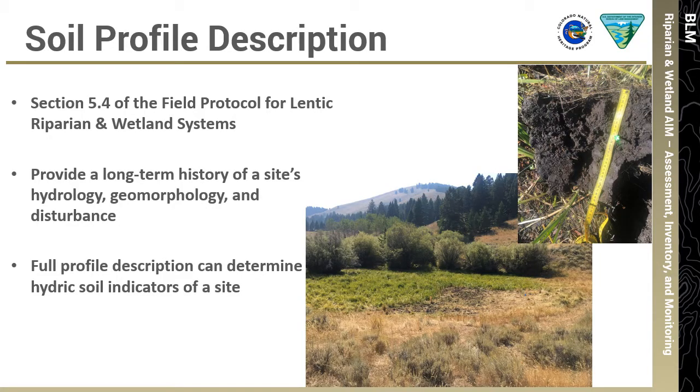Soil profiles are an important part of understanding the long-term history of a wetland site. Soils within wetland and riparian areas may undergo periods of inundation, saturation, and resulting depletion of oxygen. By completing a soil profile description, we can determine any hydric soil indicators shown in your soil profile and piece together evidence of what this hydrologic influence has looked like in the past.